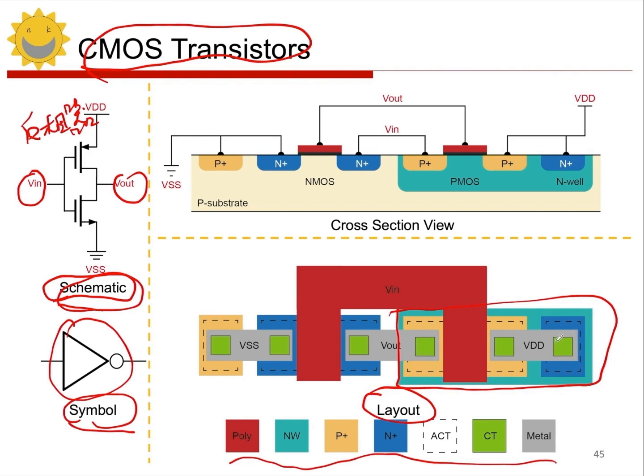After we have the active regions, we need to create the polysilicon for the gate. This way we can form the gate. Next we have the source and drain injections, as well as the substrate contact injection. Note that the type for the substrate contact is N-type, while the source and drain injections are P-type. Then we connect them using contacts and metal. Since this is an inverter, the source of the PMOS needs to be connected to the substrate, so these two parts are connected with metal, right?